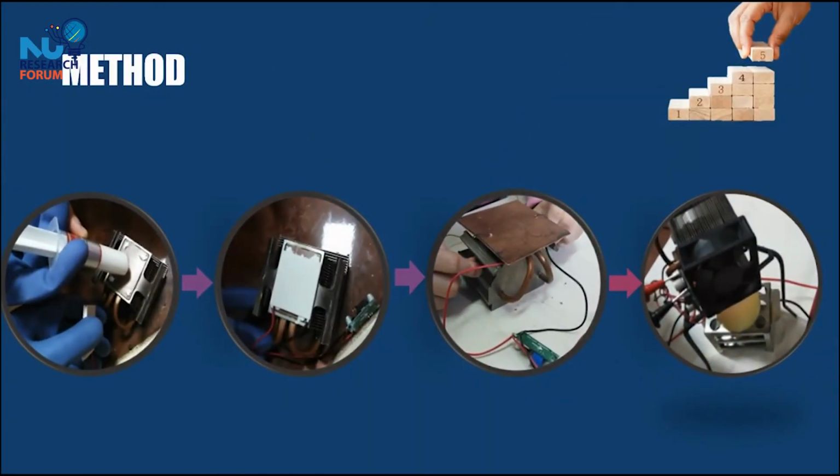To obtain the required design, norms, mechanisms, and techniques were followed, and those are represented in the following stages. First, bringing a heatsink, then putting a layer of thermal grease on its base, which has a copper piece. After that, putting a thermoelectric cooler above the base of the heatsink, in which the cold side of the thermoelectric cooler faces the heatsink. Then, placing another layer of thermal grease on the thermoelectric cooler on the heat side, and setting the copper sheet that was perforated with 2 holes.